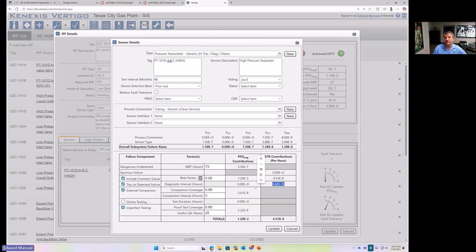So this use of external comparison, you really need to know what you're doing and how you're configuring your SIS and how you're implementing this, or you could end up with a very wrong answer. So my first warning is, if you haven't taken this training that I'm giving you right now in this webinar and truly understand what you're doing with the external comparison, just don't use it. Just rely on the diagnostics that are the internal diagnostics that are built into the transmitter.